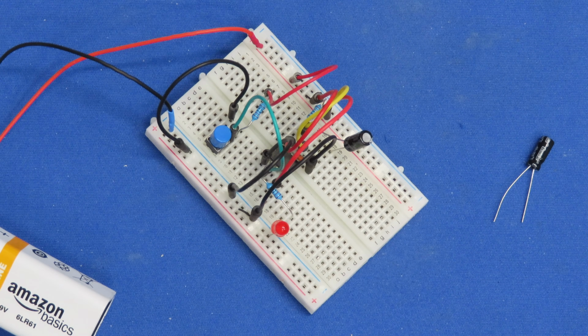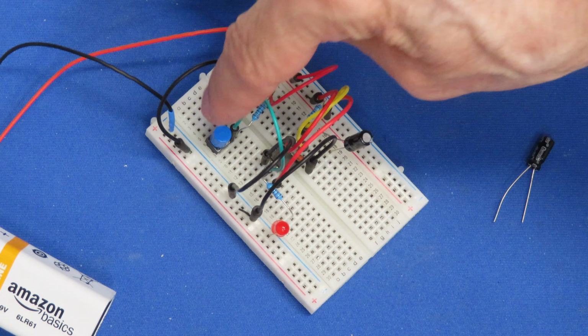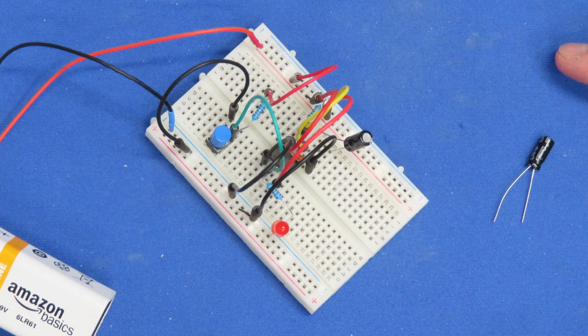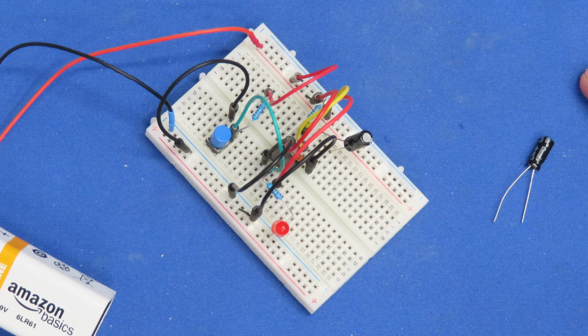Now here's our monostable mode demonstration. Remember, in monostable mode we are triggering the timer, and in this demo we're using this push button switch over here, but we could very easily be using an incoming pulse that was going low. It would do the same thing, and the output again is our LED.